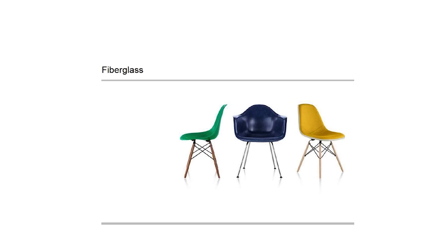And so what we did at Herman Miller is we transitioned away first from fiberglass to polypropylene. So we began making this chair more environmentally friendly through an alternatives assessment by using the polypropylene material. And as designers are known for, they came back a number of years later and said, we really want the fiberglass design to be sold again. That's the look everybody wants. The polypropylene doesn't look like the fiberglass matte look. And so we had a challenge of trying to find a fiberglass that was a more friendly product that had no chemicals of concern that we could find through our screening processes.